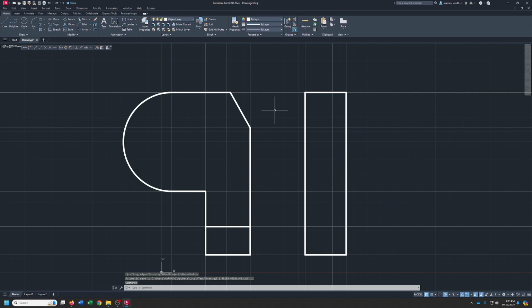We've got two circles to do. One's going to be right here, and the other one's going to be right there. They're both diameters, so do a diameter on this one of 0.625. And then the diameter of this one is 1.75. So there's those two.